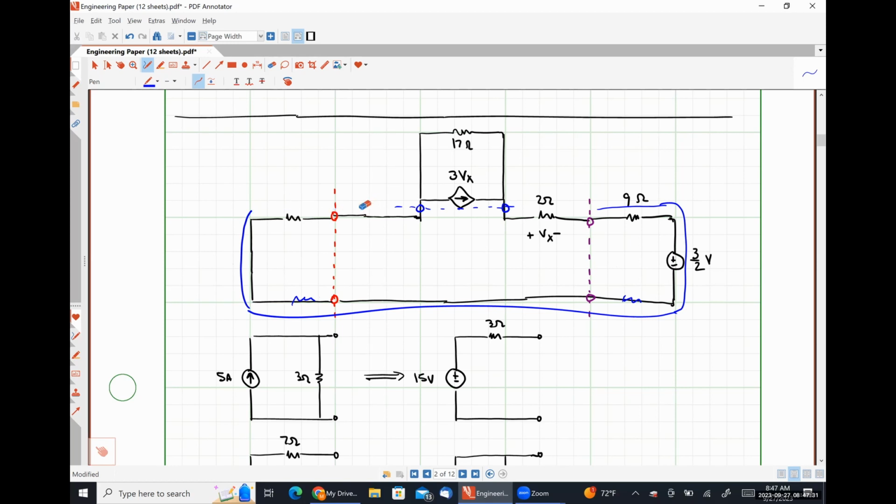Yes. Give me just a second to redraw this, and then I need you to re-ask your question because I didn't quite understand it. If the 3.5 volt source were a current source, would those resistors have still been in series? Absolutely, because they would still have the exact same current flowing through them.